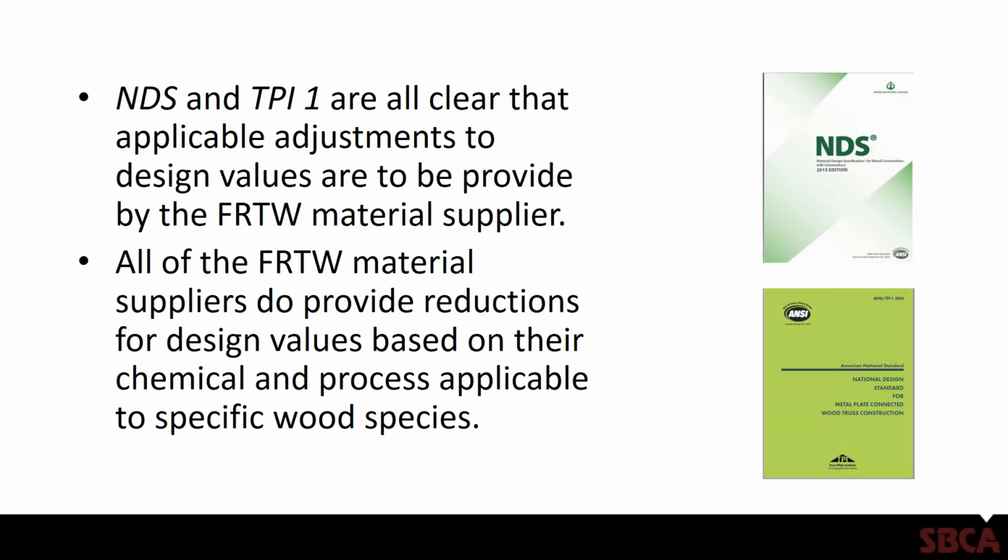So just to reiterate, both NDS and ANSI TPI 1 are clear that applicable adjustments, if you're using FRT for the lumber, those adjustments to the design values have to be provided by the material supplier. And all FRTW material suppliers typically do provide those reductions.